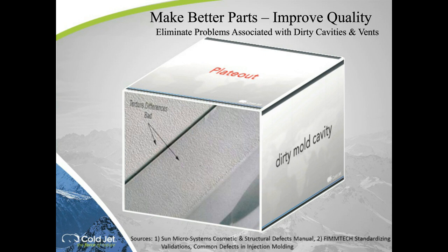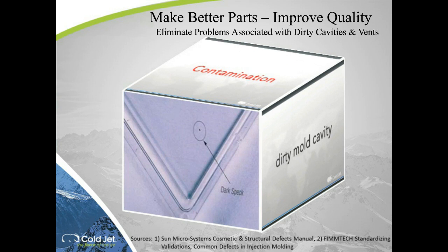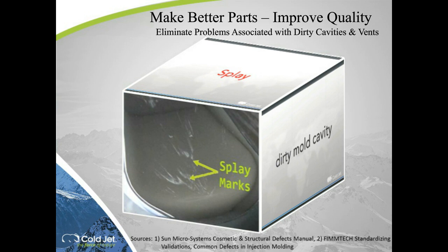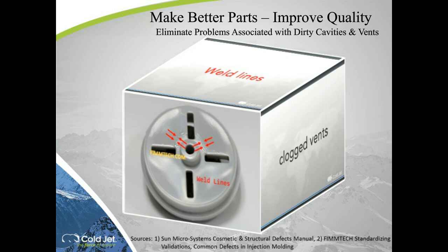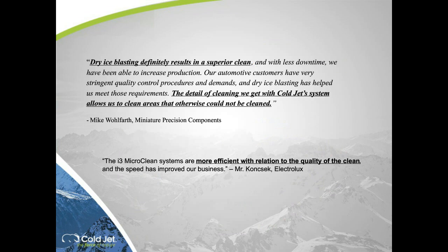This particular picture is more of an automotive application where gloss control levels are a problem. But you can get plate out if the cavities are dirty. You just get flat out contamination on a part if the cavities are dirty. You can get splay as a result of having a dirty cavity. All these things can be proactively addressed, even down to the weld lines, just by cleaning the molds quickly and easily using dry ice. People who use dry ice tell us this.